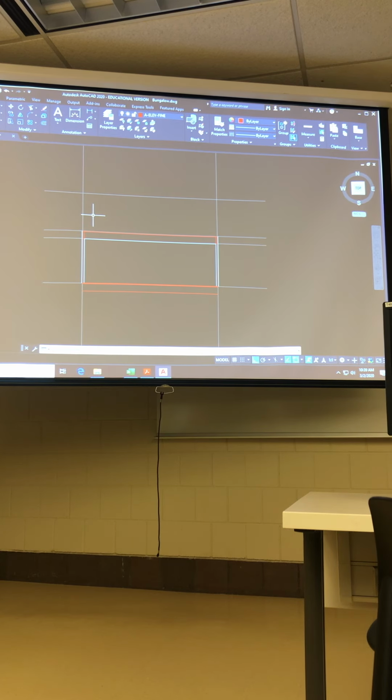And there actually is. This wall in the bedroom happens to also be where that web member is in my truss. And there's a dimension on the floor plan drawing here of 14 feet from face of framing for that wall to face of framing for this wall. Or another way to think about it is the center line in this room is right down the middle, and I have 7 feet from the center line of that room to the wall on either side. Is everybody still with me?